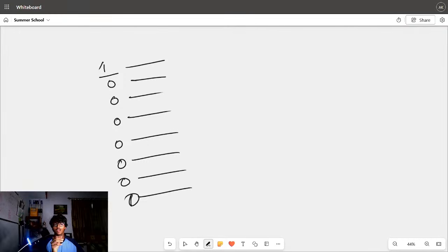Now there is a way for you to compress the same information into 3 lines instead of 8. It's gonna save you much more space and circuitry, because you already know that only one of these is going to be high at a time.